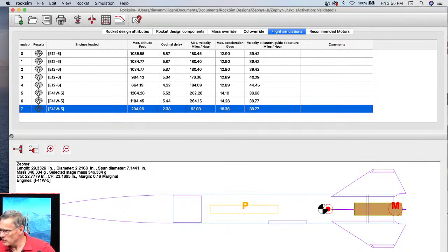But Low Budget Bob's asks, if a rocket doesn't turn into the wind, should it be balanced to be more overstable and turn into the wind? This is a subjective answer. It depends on what you desire for the flight. If you want it to turn into the wind, then make it more overstable. If you don't, see, what I was hoping here on this particular flight was that the rocket wouldn't be affected by the wind so much.